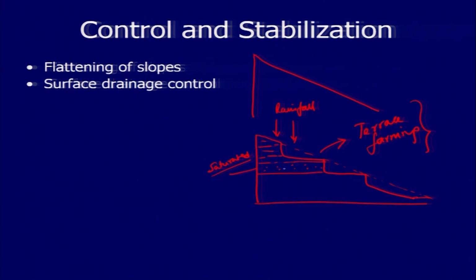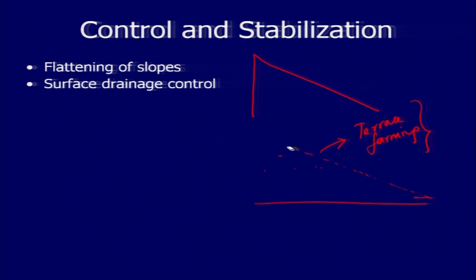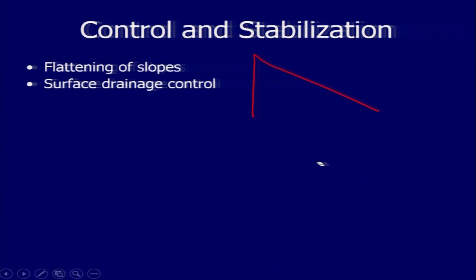I have drawn this horizontal, but usually you will not find that, because the inclination itself shows the part of the deformed structures or the inclined stratification. So if you have inclined strata, then you have this accumulation here, and this is what we call a vulnerable unit, which can slip in future if it becomes saturated.